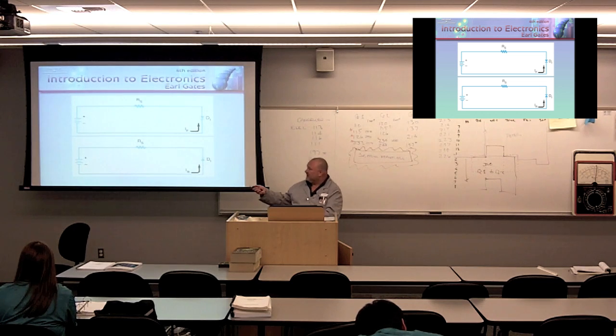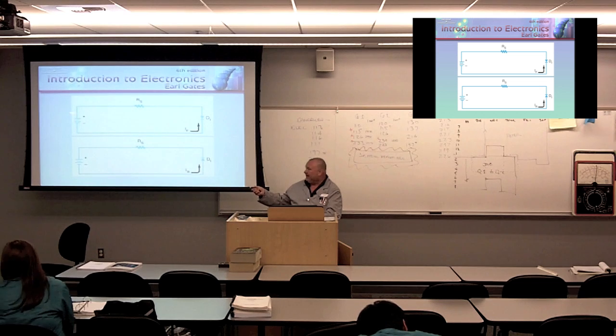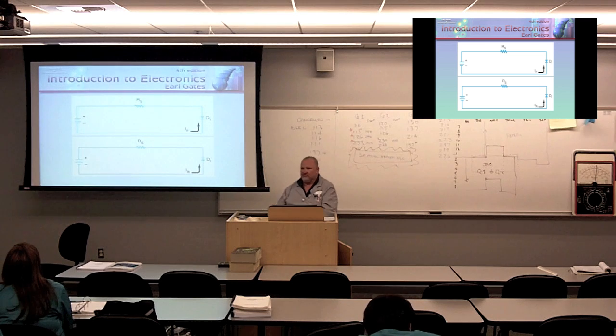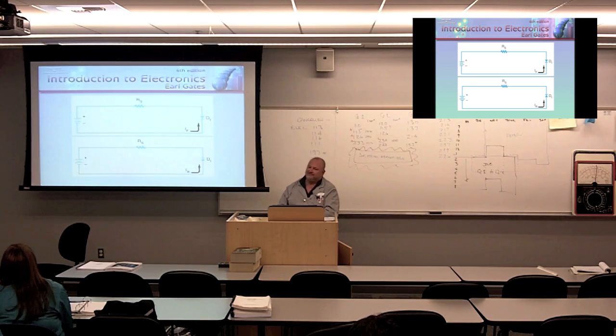I'm going to ask you some questions. This right here is a 10-volt DC power supply. It's connected to the circuit right here. This is a silicon diode. What voltage will be present across this resistor? 9.3? How in the heck did you come up with that? Absolutely. Very good.